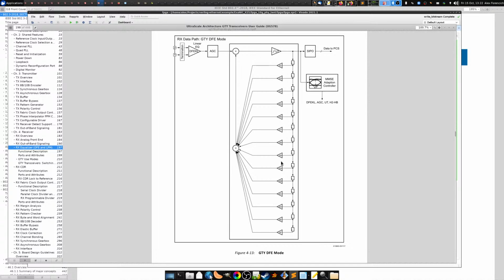And this is the simple part, the actual equalization, but how do you determine all of these parameters? This can change over time as the voltage and temperature change in the transmitter and the receiver. That's going to change how the analog components work.